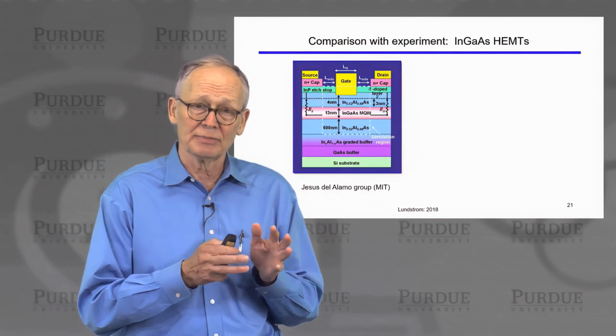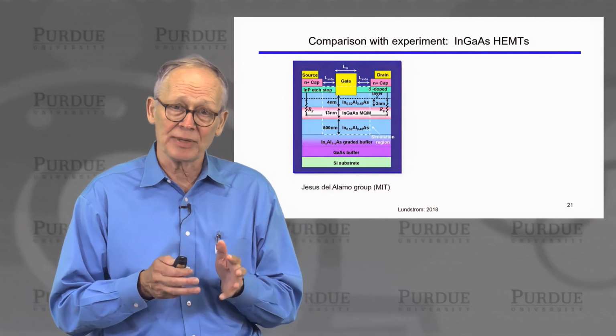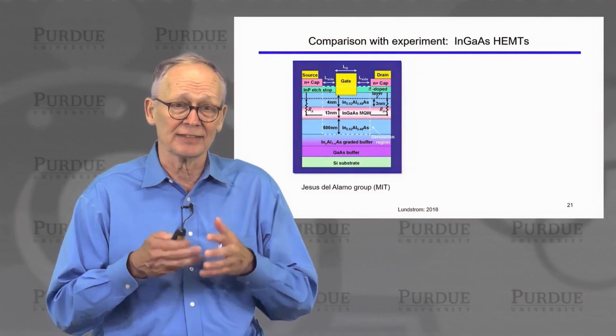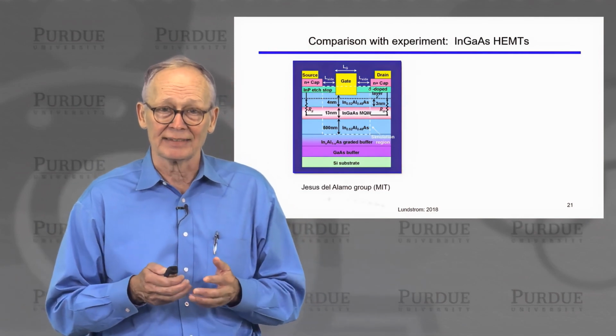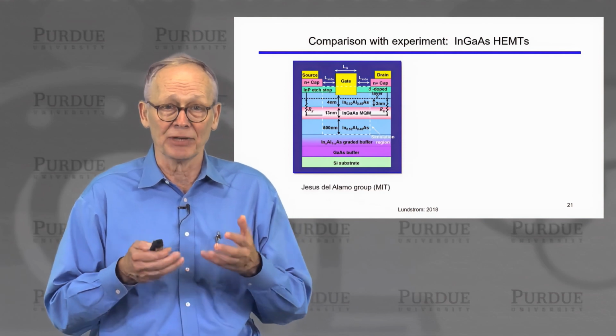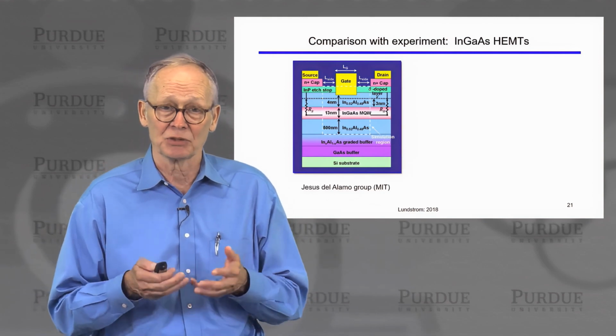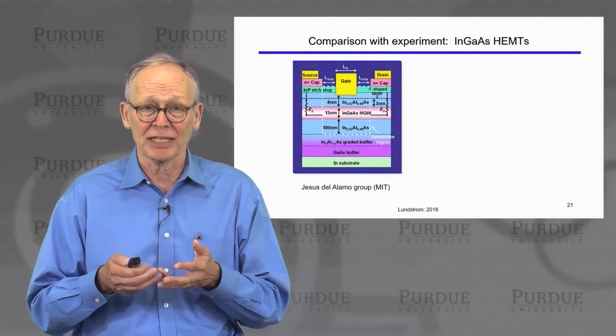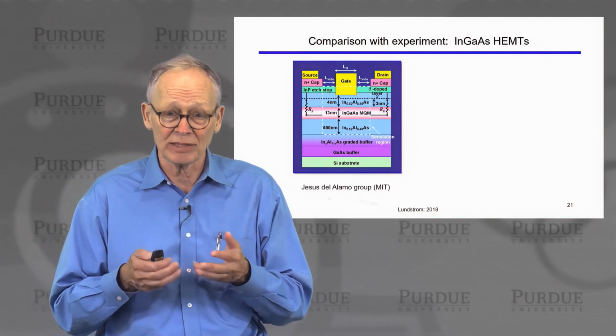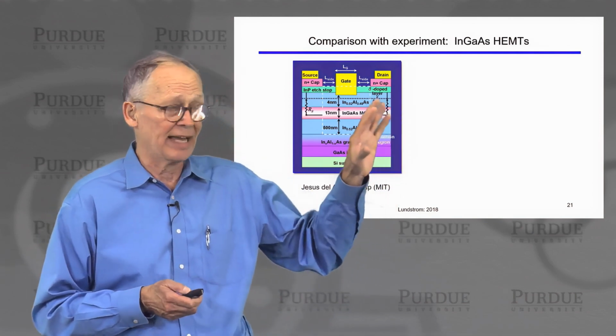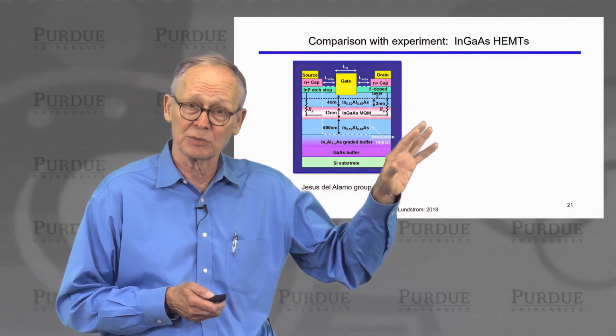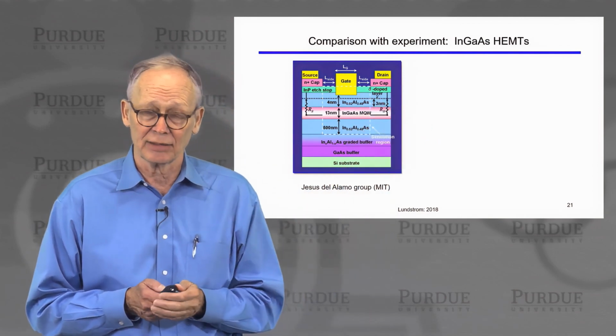Now, if we draw an energy band diagram for this device, it's very similar to a MOSFET. Its operating principle is a barrier-controlled device where we're controlling an energy barrier with a Schottky barrier now instead of with an MOS structure. We can then analyze this. In fact, it can be analyzed with our virtual source model very carefully.